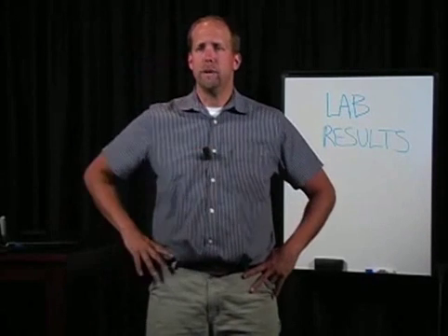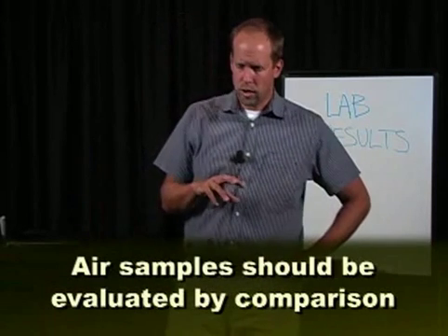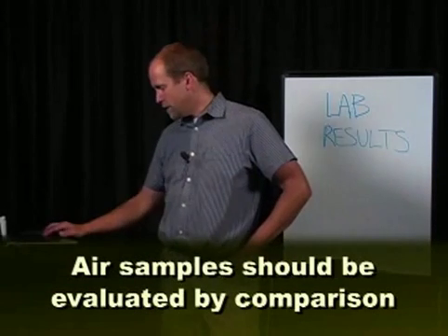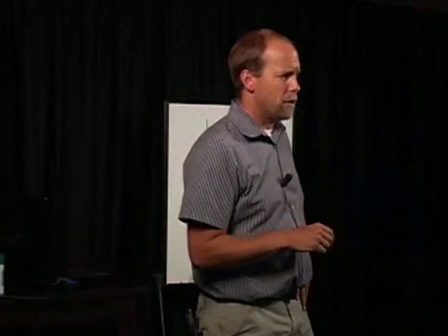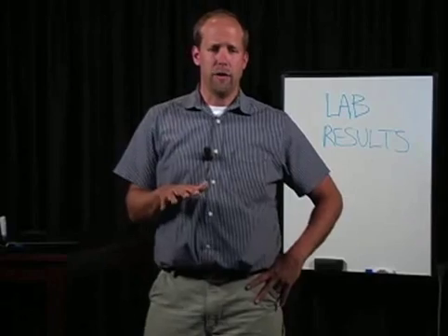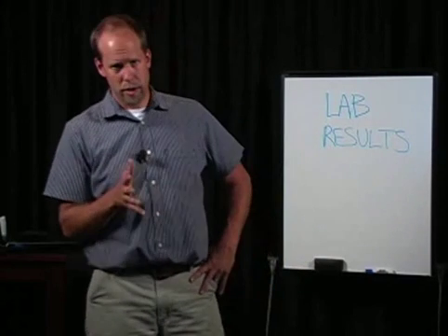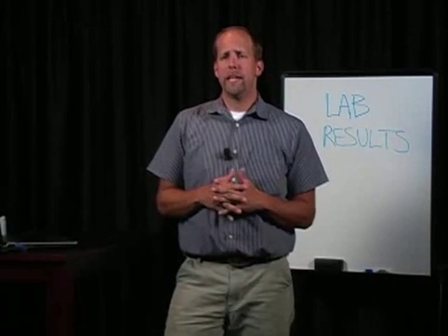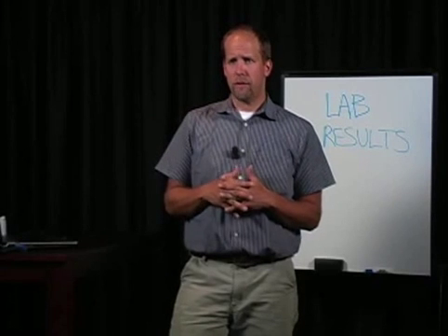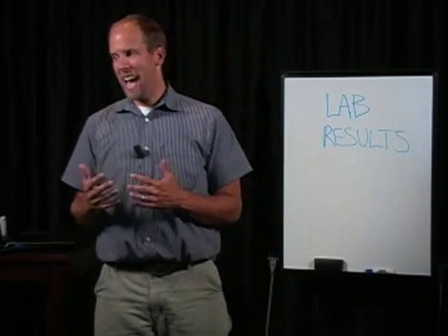Air samples should be evaluated by means of comparison, indoor to outdoor, and by fungal type. In general, the level and type of fungi found should be similar, indoors as compared to the outdoor air. Differences in the levels or types of fungi found in air samples may indicate that moisture sources and resultant fungi growth may be problematic.